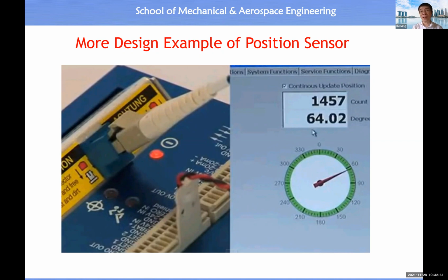All right, the reason is because inside the industrial robot, there is no presence of an absolute encoder. So with this feature, you can imagine, why not incorporate an absolute encoder inside the design of the industrial robot? Then in this way, you do not need to do the homing operation. Okay, today's practice is like that. We do not use an absolute encoder in the design of an industrial robot. We use a velocity sensor. Right, so this is just for you to know.